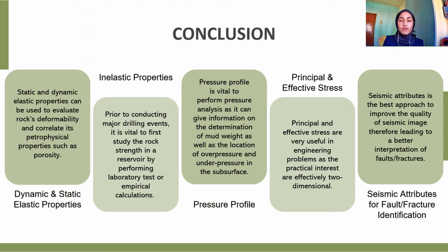We have reached the end of our presentation, where we have discussed thoroughly 5 different topics. I would like to summarize each of the topics in a short note. Firstly, static and dynamic elastic properties are useful in order to evaluate the deformability of rock and correlate it to its petrophysical properties. Secondly, in inelastic properties, it is very important to first study the rock strength in a reservoir by performing laboratory tests or empirical calculation before conducting any major drilling event.